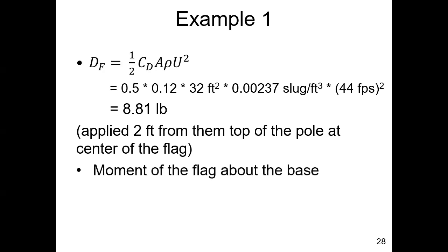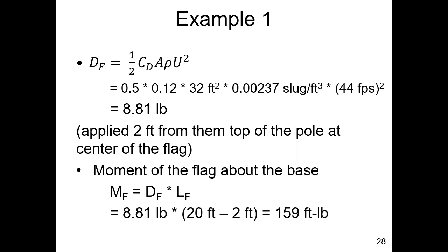So what would be the moment of the flag about the base? That would be the drag force on the flag times the moment arm of the flag to the base, which is, again, 8.8 pounds times 18 feet. So even though the force wasn't that great, since it's much farther away from the ground, that's a pretty significant moment when you compare it to the moment of what the pole was itself.